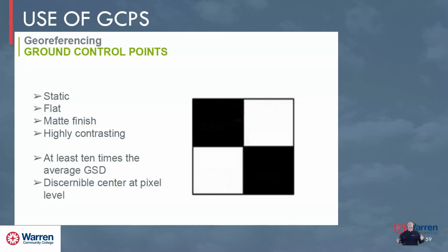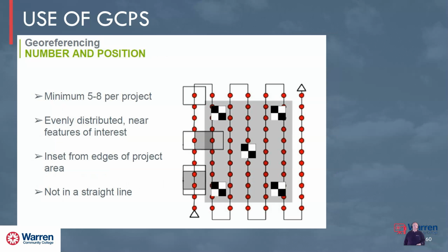And so when you got back, you could take all these scaled measurements and accurately put more accuracy into your model. If you knew the exact, like the ones we have placed at the college that you'll walk out around the Smith Training Center and see, then you can go back and just plug in the actual numbers of GCPs, and I think that's going to be in lesson 3 of your student manual. You'll learn how to plug in if you had ground control points, and this will become more clear as you go through the lessons in the manual as well.